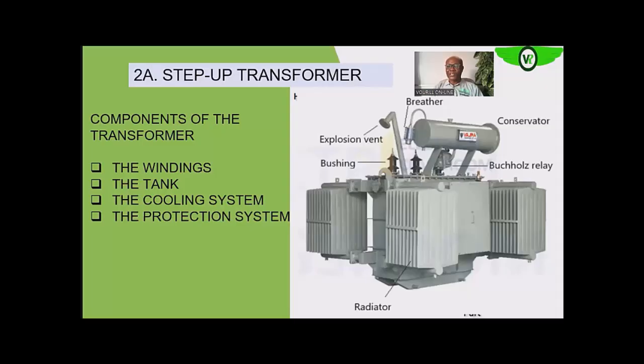So the explosion vent helps us to avoid such a situation, in that the pressure disc around that vent will break and release the excess pressure from the transformer. So the issue of explosion will not be there.